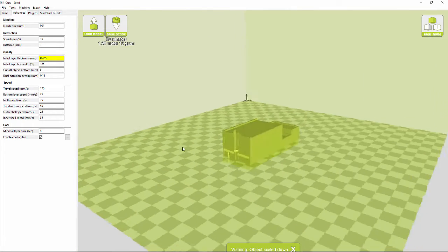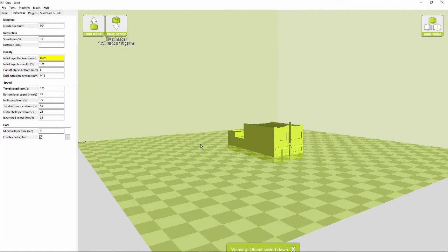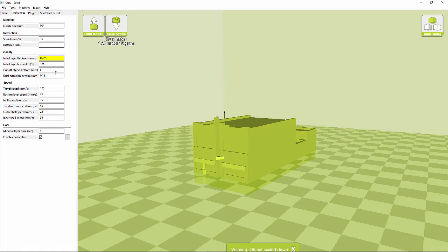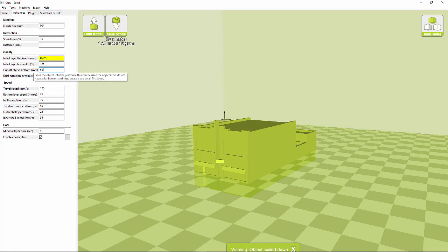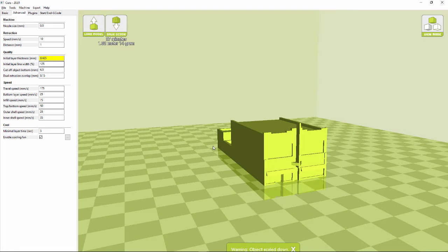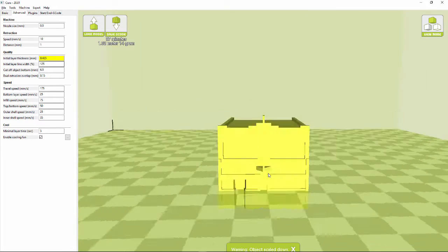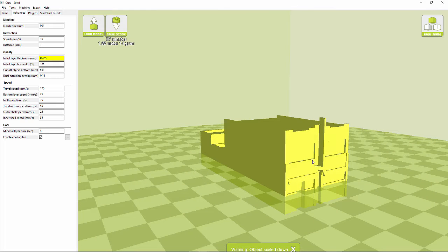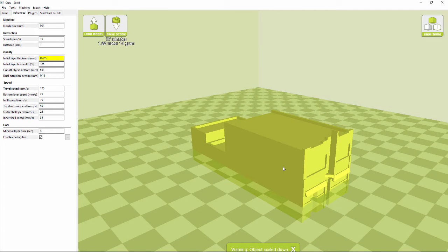When I come into something like Cura, I want to be able to drop this model the exact same number each time. And 10 feet scaled down to millimeters, I believe, is right at 6.5. And so I can cut off that bottom 10 feet of the building to scale on every single building that I did that with, knowing then the building isn't going to be out of scale in terms of its height.